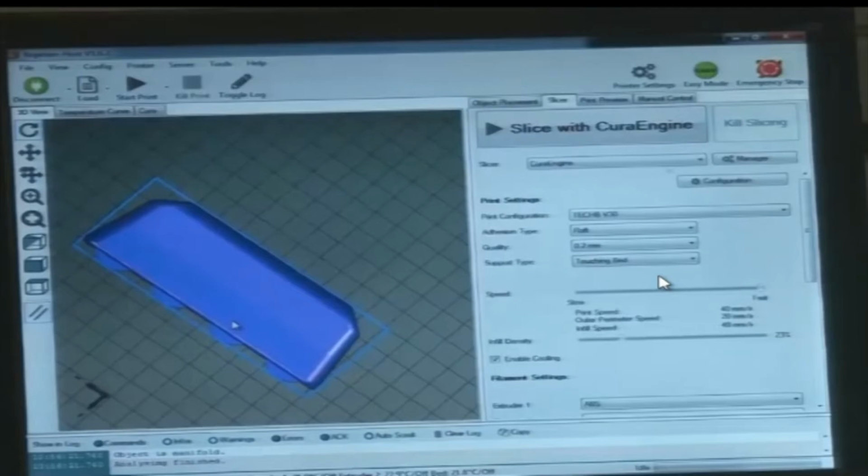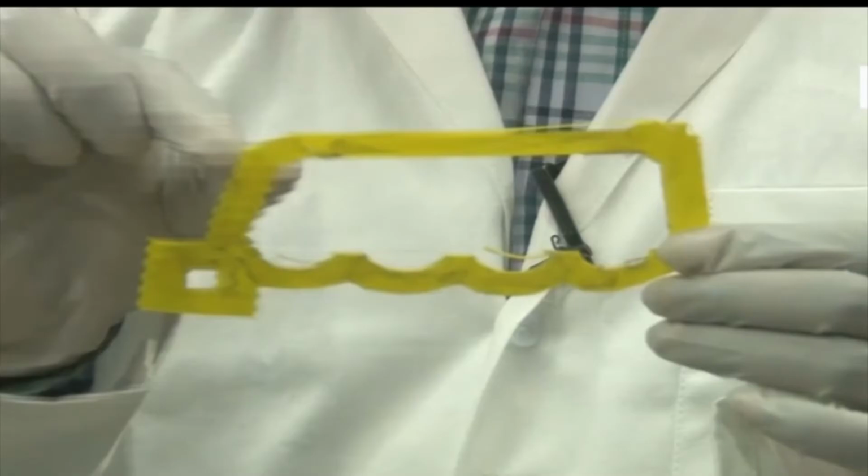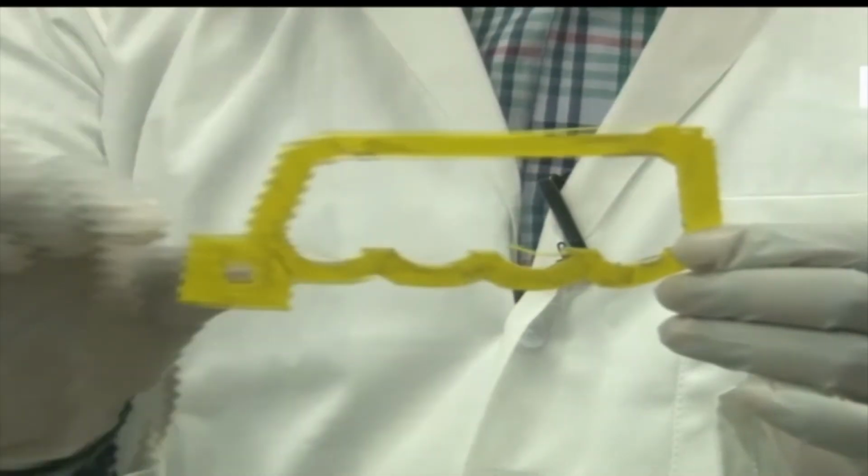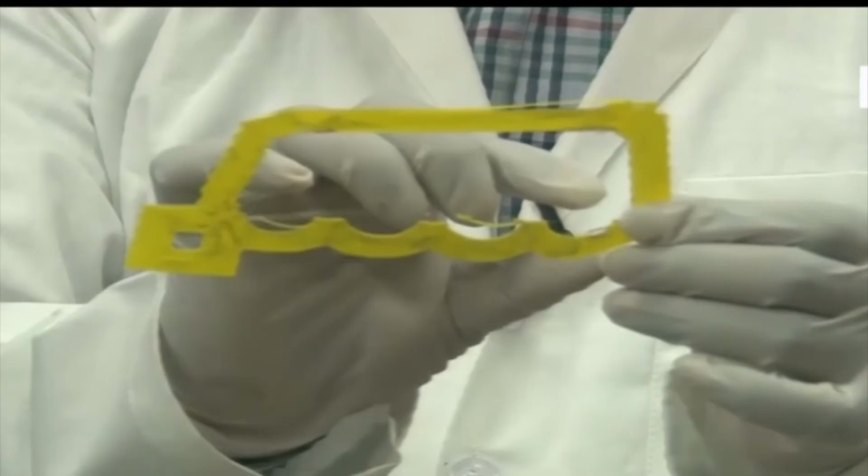So this is brim that is taken off from the job that is prefabricated. This is the model that will be developed. This is the pocket. This extra material is brim, this whole material is brim. It is taken off from the project that was manufactured before. So this will stick with the bed properly, and this enlarged area, the first layer, will provide a good holding with the bed.